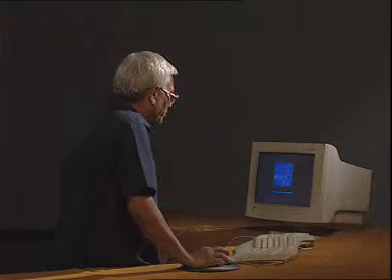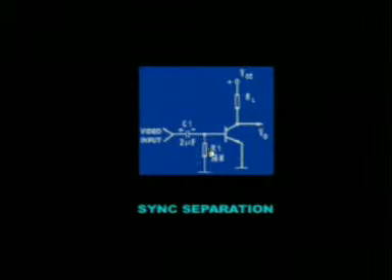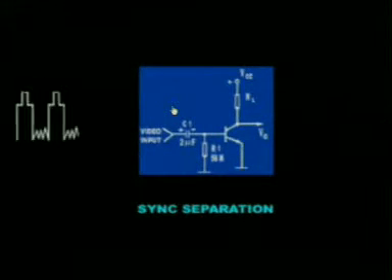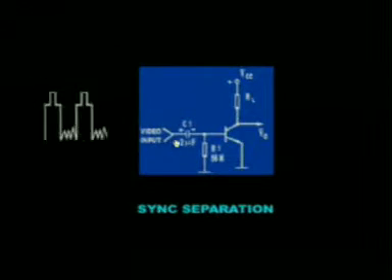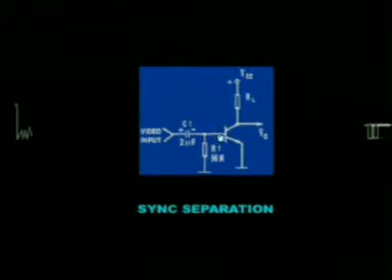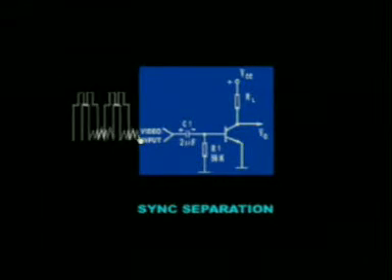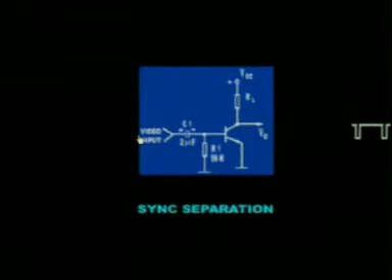The self biasing through C1 and R1 maintains the level. See here again, the composite video signal is entering here at the base and going through the sync separation, and after a delay this comes out from the collector. As and when this video signal is entering, it is not coming out at the same time from the collector. There is some delay.